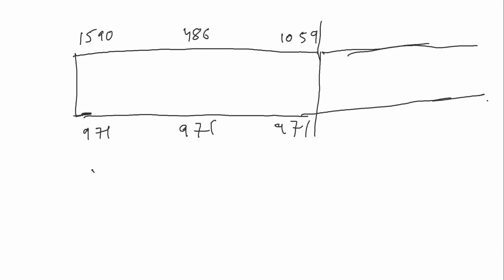In beams, maximum they are going to use 12 dia rods and 16 dia rods, and if the load is very high then you go to 20 dia rods. If you go to 25 dia rods, then the beam must be big or heavy, like 500 mm depth or 600 or 700, more than 450 is better. Then you can go with 25 dia rods. But if it is 450 mm or 500 mm beams, below 500 it is better to restrict the bar diameters to less than 20 dia.